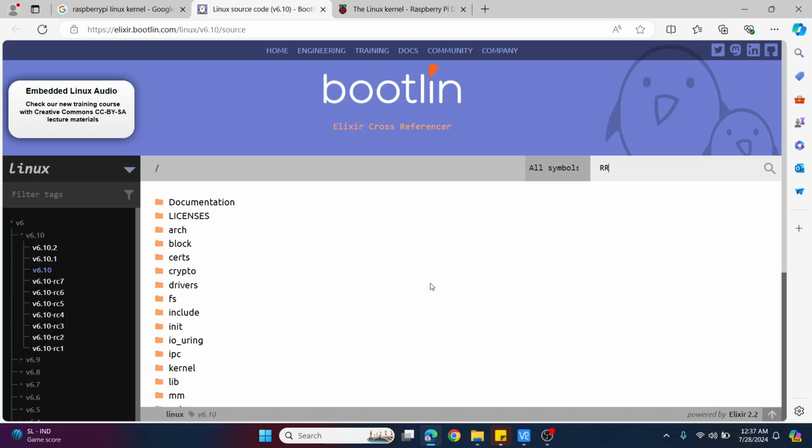Then comes a hot trip point. The name of the trip point is hot. Hot means that it has really reached some critical, important temperature, and now you need to act. You need to either put it in idle, and you might want to turn off some of the features on the motherboard, or I don't know, there can be several things you can do when a hot trip point is reached.